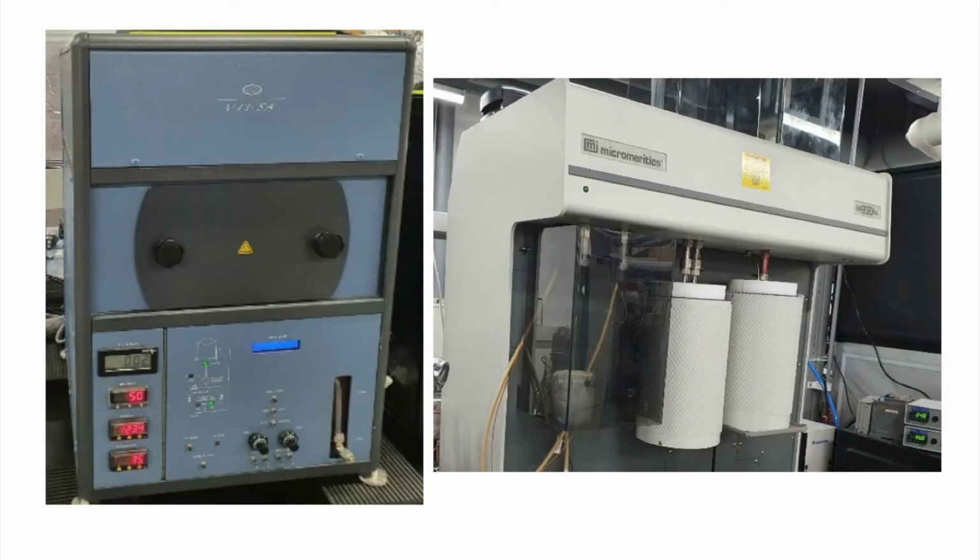And these two are the sorption measurement systems. The first is, like I said, for sorbent-solvent separations, and we can measure the sorption capacity of the solvents, different VOCs or actual alcohols, and we can compute the difference in diffusivities based on the time scale of the sorption using this simple equipment.